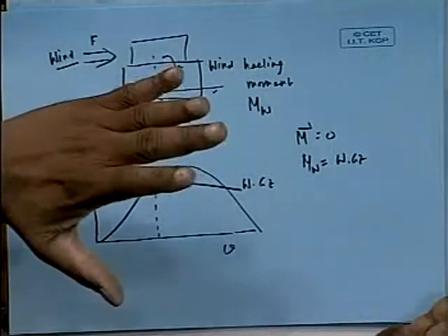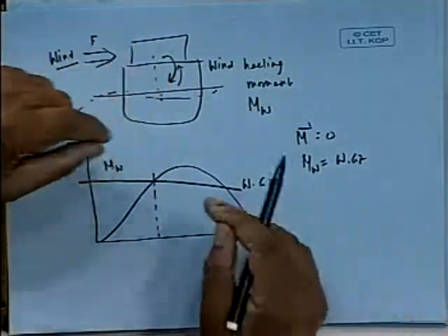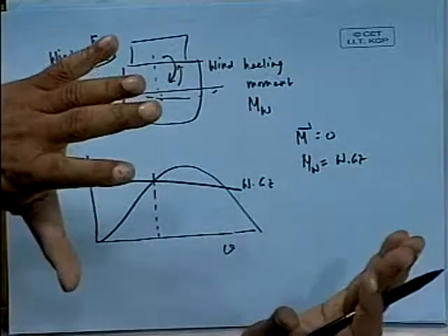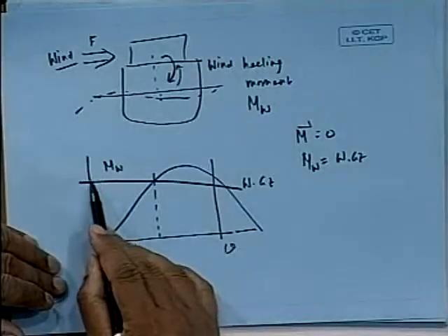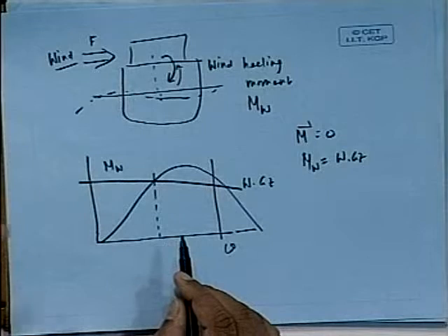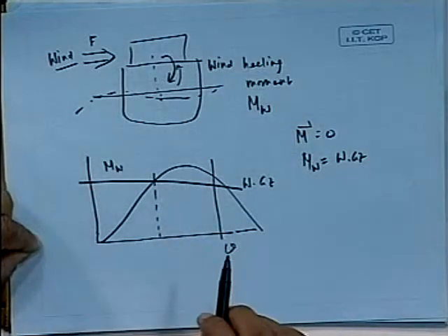It will go up to that point, but at that particular point the two moments are not the same, so it cannot stay there. The moments are non-zero, so it will again come back on this side. Then again it will go down, so it will oscillate a little bit till the energy gets dissipated. There will be viscous phenomena like wave formation that will eventually dissipate it. But in the first shot, it will go to some angle where the work done by the heeling moment must equal the work done by the restoring moment.